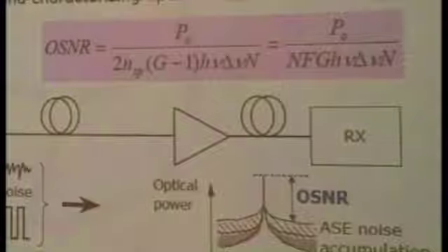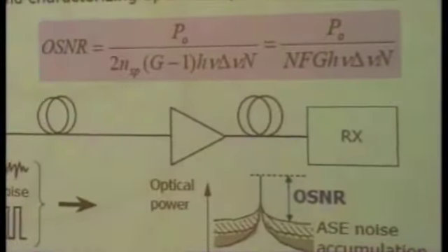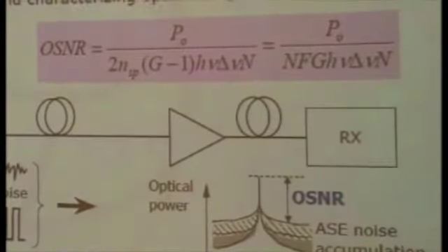So in the budget, there is no minimum receiver sensitivity. This is because the receiver sensitivity is not important in this case, because the main noise source is the optical amplifier noise. But the criterion is also the same, 10 to the power of minus 12.